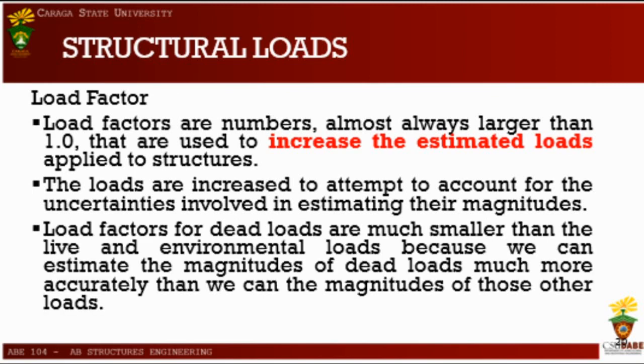Next, load factor. Load factors are numbers almost always larger than 1 that are used to increase the estimated loads applied to structures. The loads are increased to account for the uncertainty involved in estimating their magnitude. It is really important to consider load factor because we're just estimating the loads. In order for us to take out the uncertainties, we will use this load factor. The load factor for dead loads is much smaller than for live loads and environmental loads because we can estimate the magnitude of dead loads much more accurately than those other loads, because dead load is an integral part of the structure.